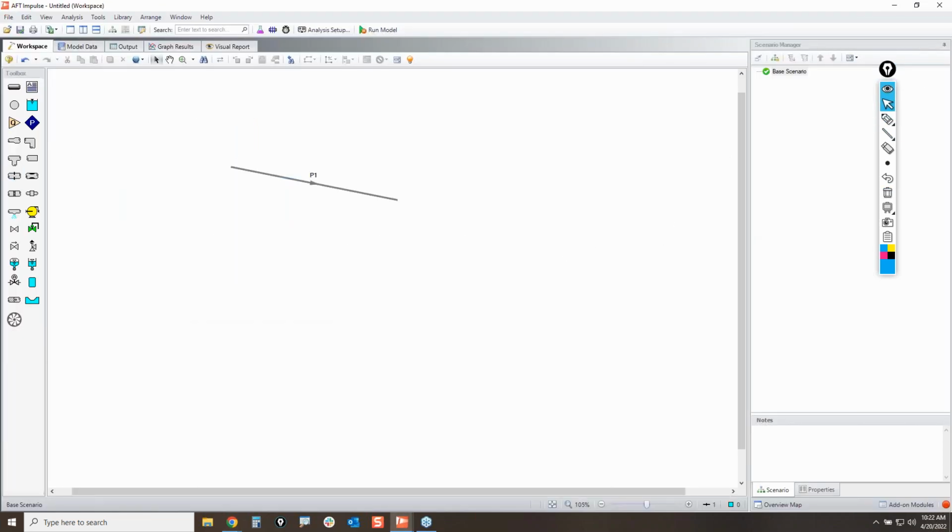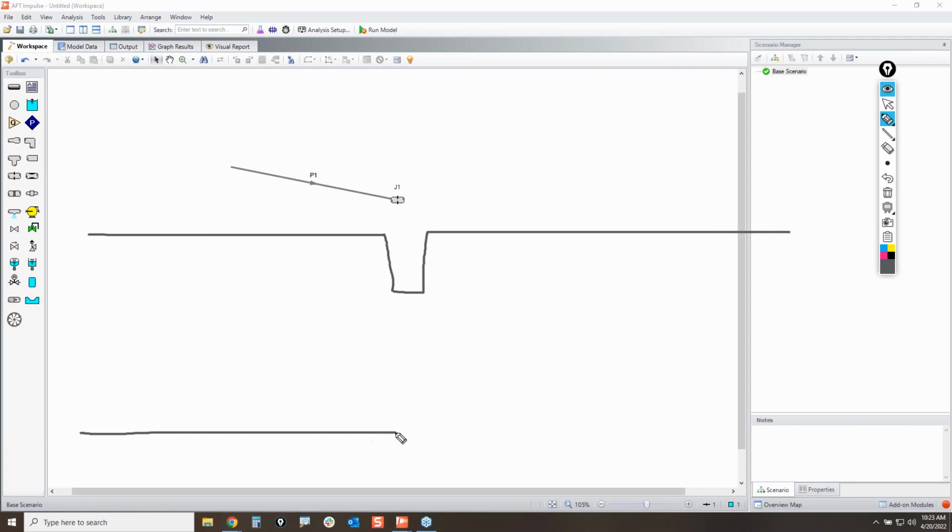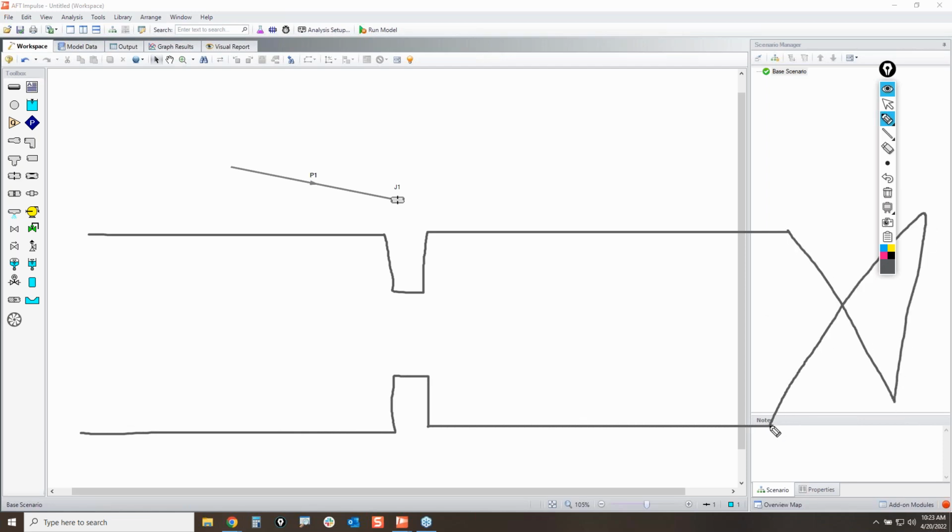Another thought is that orifice plates can potentially be a reflecting point for transient water hammer waves. And that is true, but the question is, how big is the actual effect? So if you have a pipe with an orifice right here, and then downstream we have a valve, and we're doing a transient on the valve where we're slamming it shut. When we slam that valve shut, we're going to see an increase in pressure at the valve, and that's going to transmit upstream of the valve.